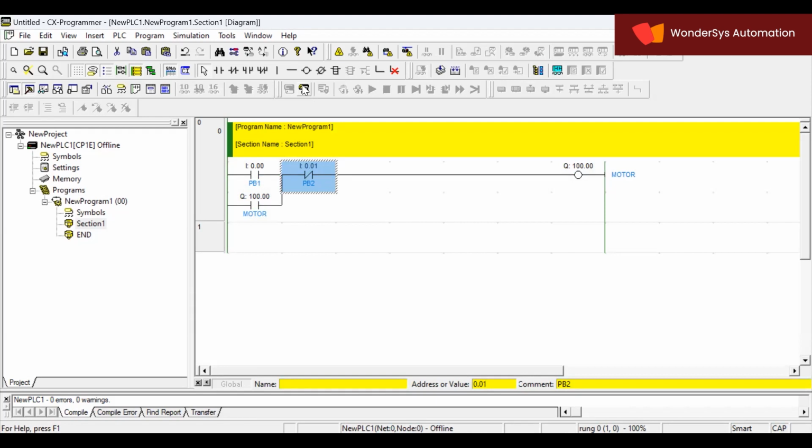It is a good habit to store the input switching, like whenever we write our program for any projects, there normally we'll be using push buttons. To store the start and stop condition in a memory, it's a good habit. So whenever we write a program, we'll store the input switching condition in the memory. Then we'll be using the memory address in our whole program.